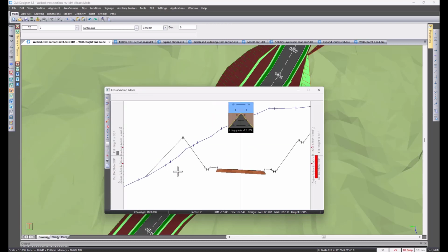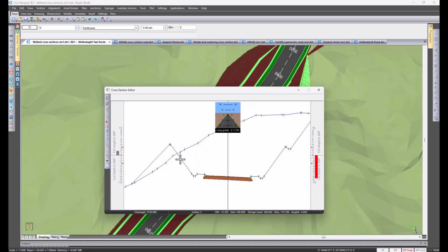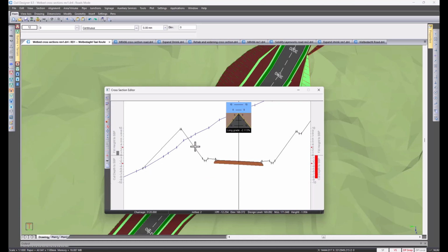And remember that the component panel would allow you to also add in new components, for example, add a cross section. But for now, today, I just want to show you how you can then delete points on a cross section. So you've got various options here on a right click. Those are also duplicated over here in the toolbar.